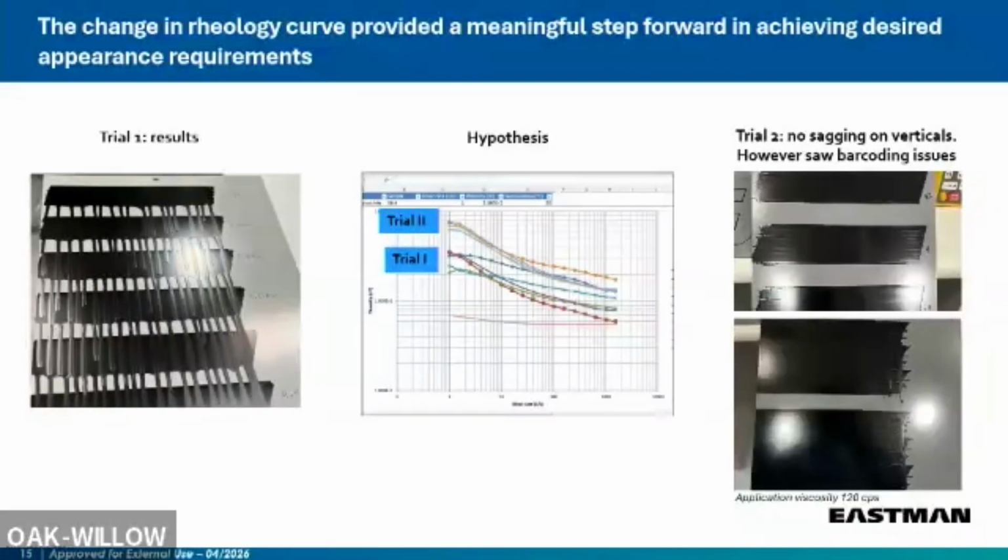Maybe the rheology curve for the other applicator may be here, maybe it may be here, but you have to have this curve. So the analytical techniques that we captured over here, the way we can use a rheology modifier to fine-tune this curve, or even play with the yield stress, will surely help because I believe all the applicators will be the same, zero overspray. It's just that the pressure, the flow rates, or the knobs they have for controlling will vary. But the basic principle will be the same.